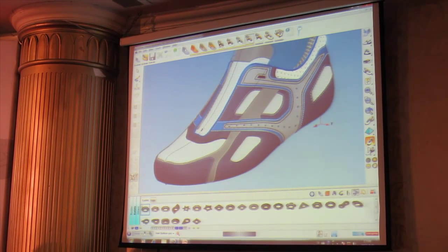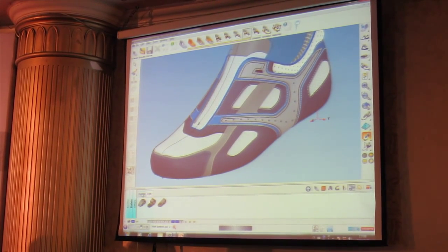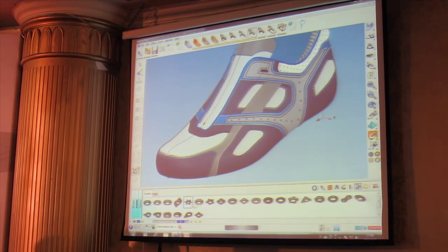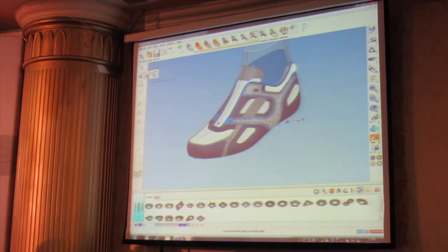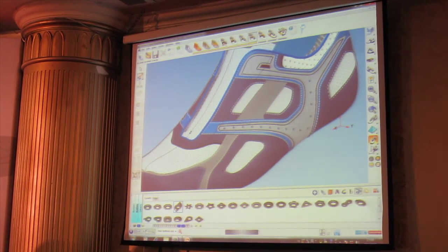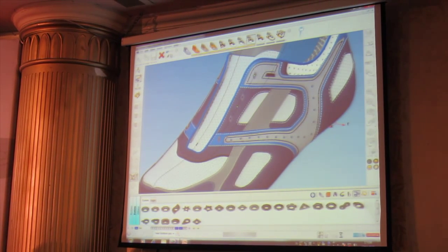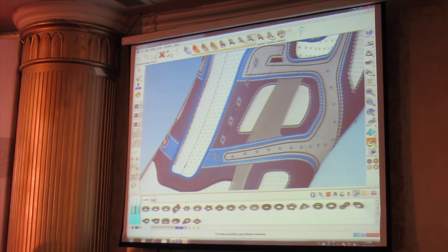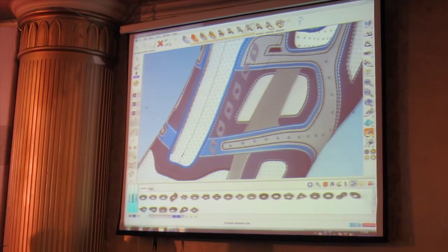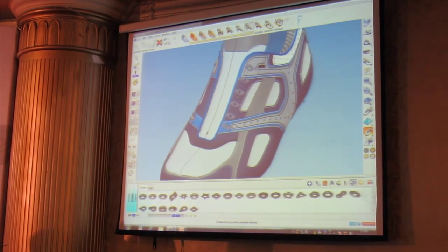So moving forward to the next creation activity, which is accessories. And again, I'll open up the library for accessories, and you can see we've got pages of eyelets and lugs and buckles, different shapes that we can apply to our designs. And again, I can either add these on an existing curve, or I could sketch them. So let me say I'm going to sketch a row of accessories, and I've selected an eyelet accessory, just to give you an idea. And again, we can change the separation values, I can increase the size, I can rotate these around, to get them exactly as I want them.